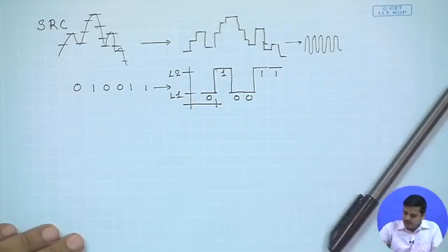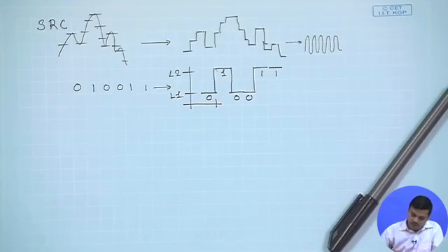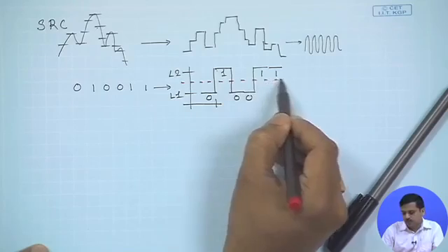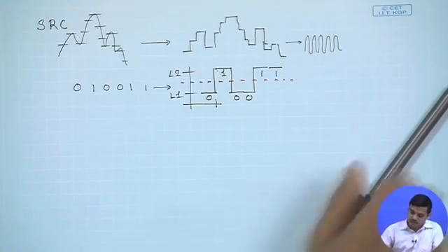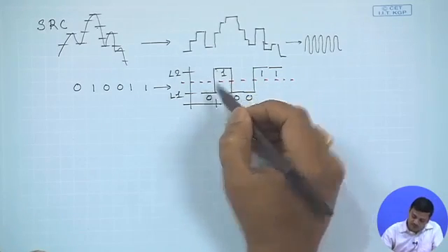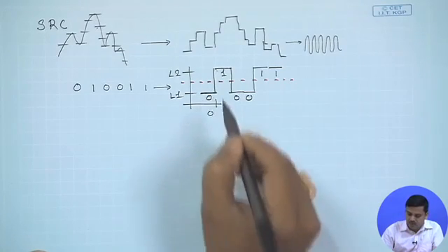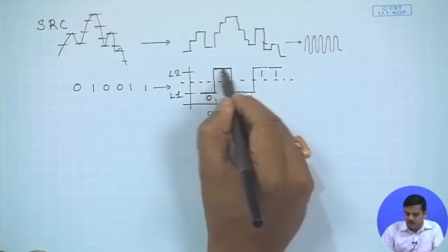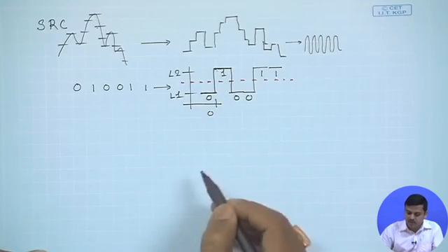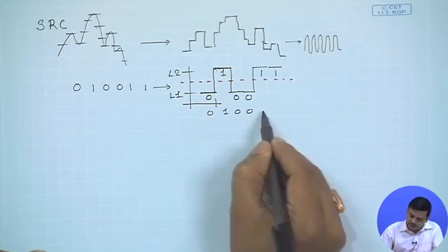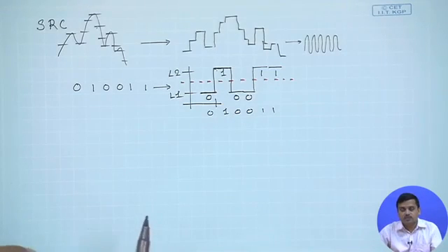And at the receiver, what you are supposed to do is we would have to choose a threshold. So if the received signal is below the threshold, I would decode this voltage to indicate a 0, and this level of the signal, let us say electrical signal, to indicate a 1, and I would again regenerate my signal. This is what we said.